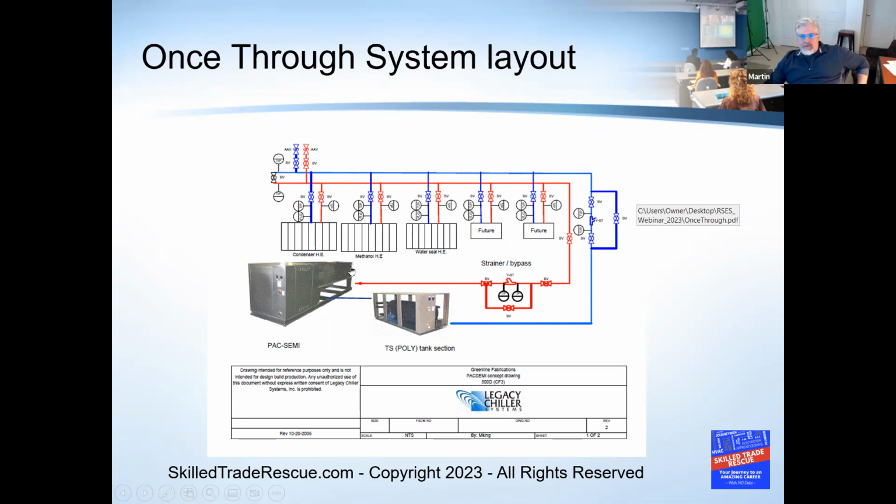So this is a less expensive application. It's not quite as complex, and this will work provided that all of these loads are fairly stable. So remember I was mentioning the temperature, the load variance. If these return temperatures are all staying the same, and the fluid temperature hitting this evaporator is within its design specification, this thing will run just fine.